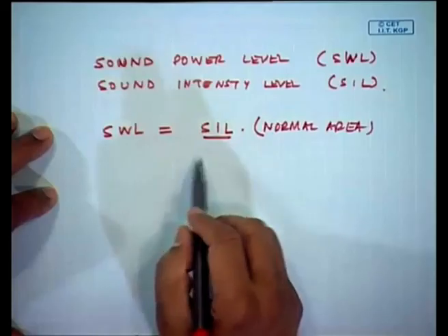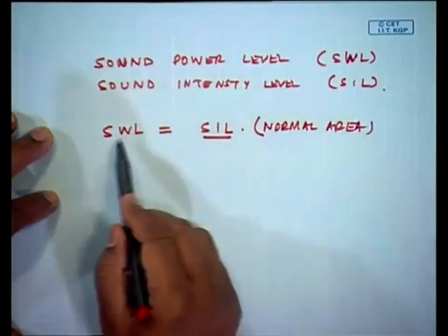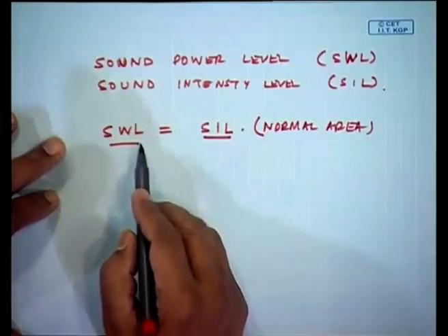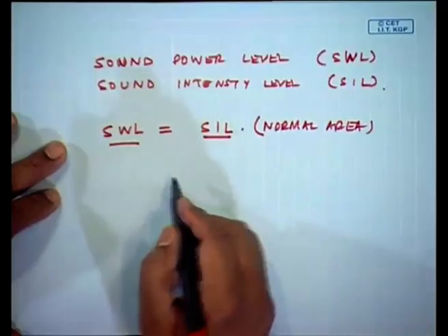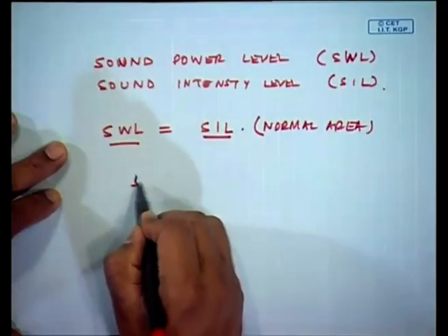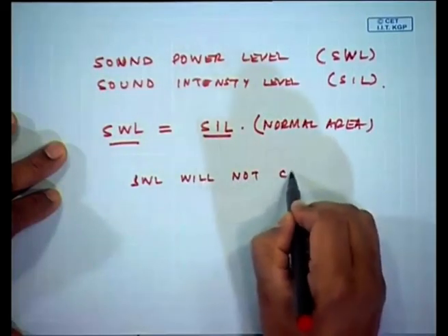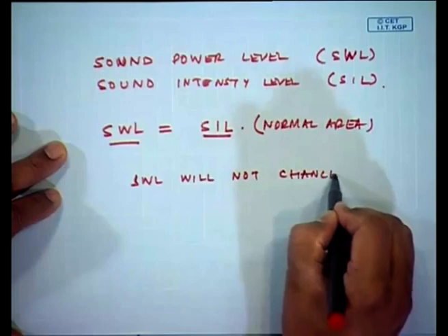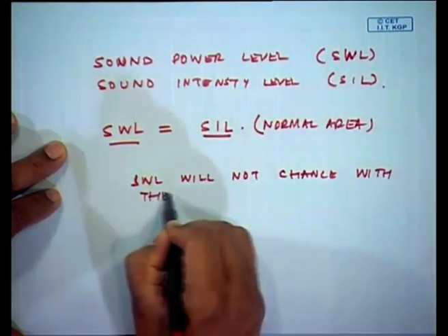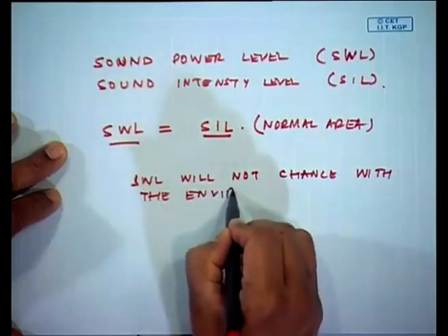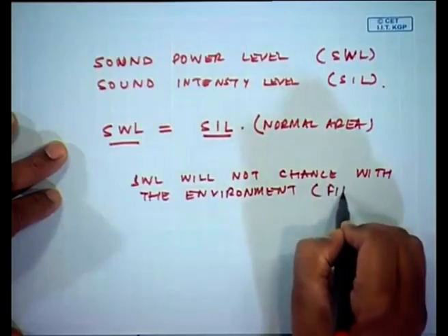Okay. There are instruments to measure sound intensity level, and then knowing the area you can find out the sound power level. The advantage of using sound power level is that the sound power level of a machinery is not going to change with the environment or field.